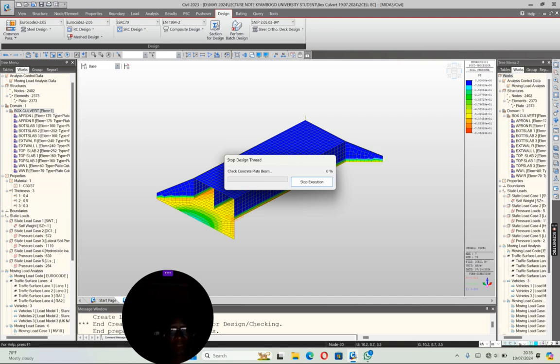Detailing, you have to do detailing to reflect exactly what you have designed. Then the quantity takeoff comes from your detailing, where you have generated your quantity of concrete and the bar bending schedule for reinforcement in accordance with the standard of detailing. Then you do the takeoff as an engineer, or you can support your quantity surveyors if you have. Then you secure a contractor and you implement.